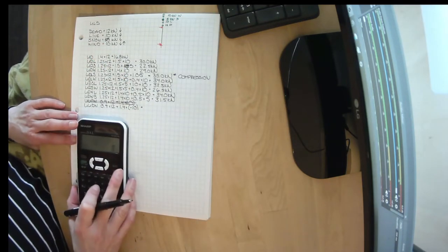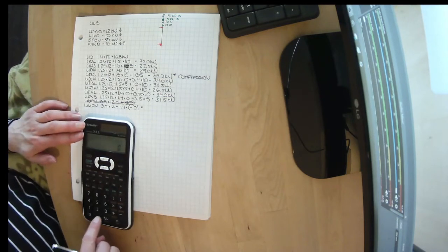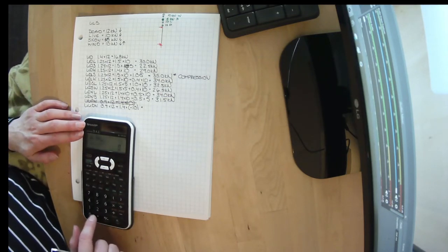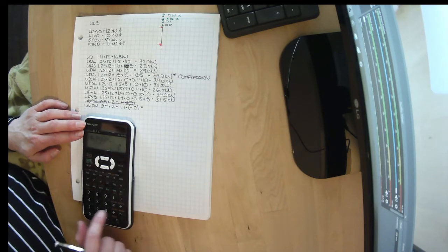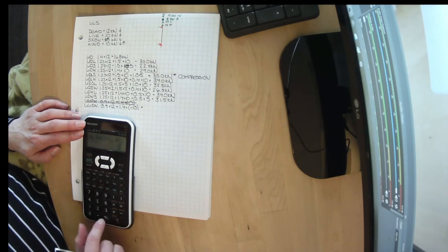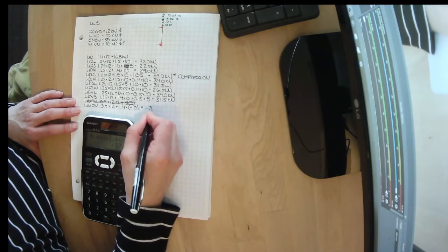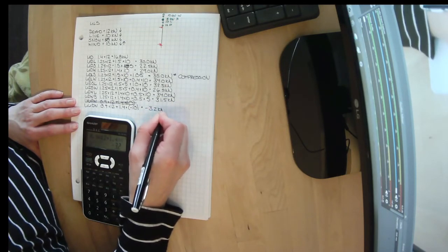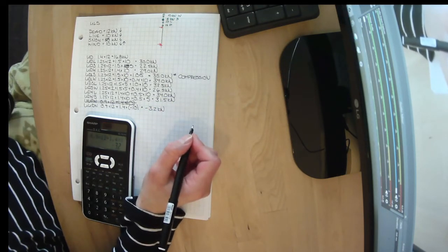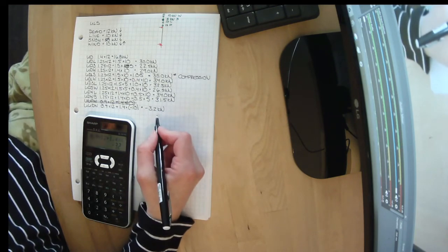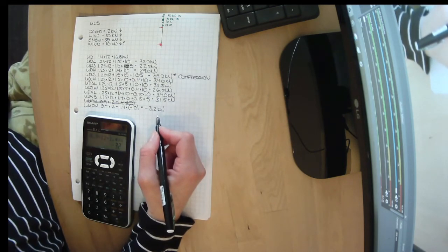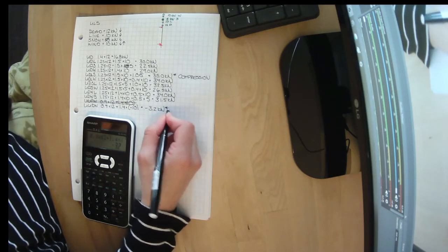It's going in the different direction from all the other load cases we've looked at. So 0.9 times 12 plus 1.4 times negative 10, we get minus 3.2 kilonewtons. So it looks like there is a chance that this could have load going in the other direction.